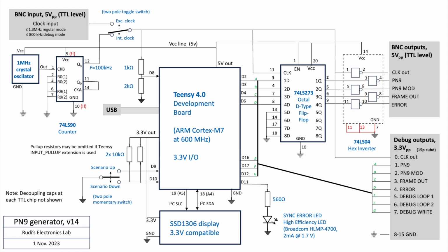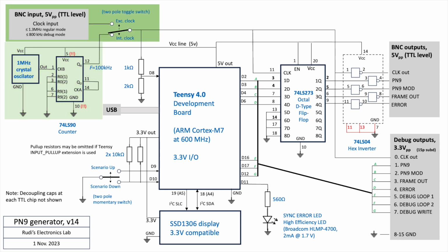Now I want to show you the circuit design itself and quickly guide you through it. I will be posting this as well, should anybody want to try to build it themselves. It's a pretty straightforward design in the end, where we got basically a clock signal which comes from an internal crystal that we're dividing by 10, so the 1 megahertz actually becomes 100 kilohertz, or we got a